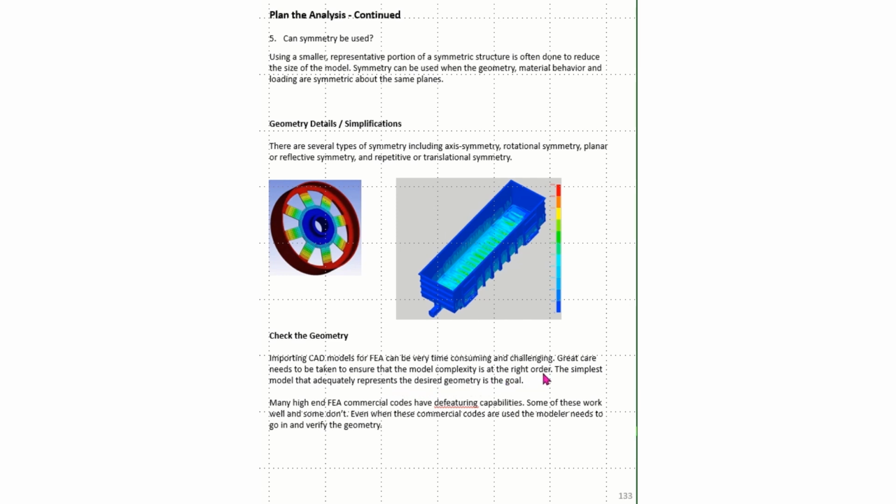Sometimes the CAD model can be extremely complex and detailed, where all of that detail is not needed or even wanted in a finite element model, because it will greatly increase the complexity of the model and possibly prevent a solution from being obtained, or require an extremely large amount of time for a solution to be obtained. So be careful in importing CAD models and just using them by default.